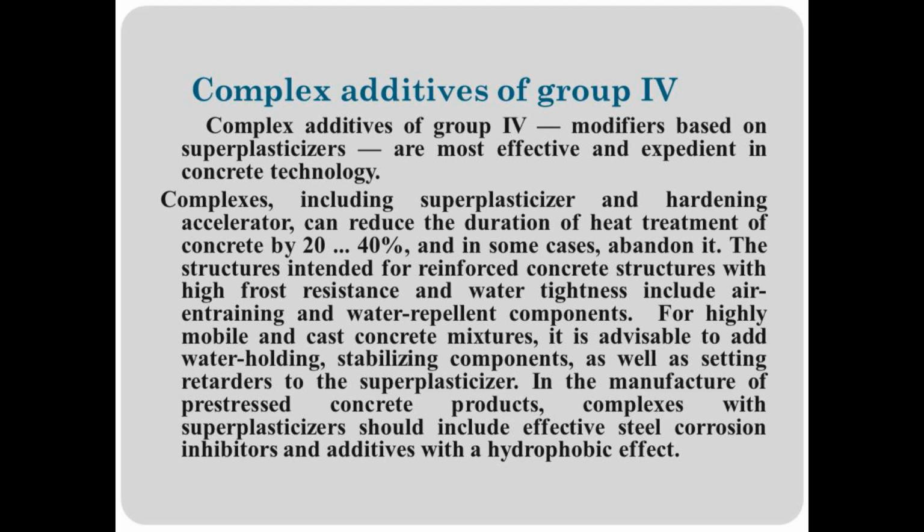For reinforced concrete structures with high frost resistance and water tightness, the composition includes air entraining and water repellent components. For highly mobile and cast concrete mixtures, it is advisable to add water holding, stabilizing components, as well as setting retarders to the superplasticizer.